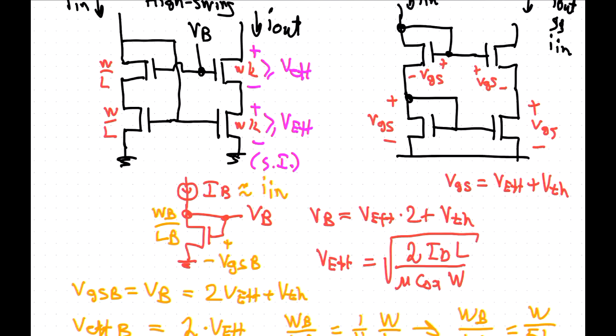So if you have one current source and you want to use that as your reference current, you generate the bias current like that by sizing this transistor. That's the bias current for all of your input transistors. And you can do the same with a P: you put that into a current mirror, mirror it up, and then you have the same structure and do the same thing for the P.